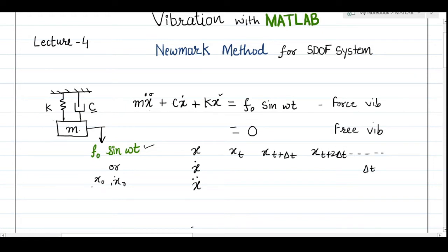What are we doing exactly? If you see the governing equation, it is a second order ordinary differential equation and it is an initial value problem. That means you want to get the response in the time domain, and for that you need to give some initial boundary conditions. Initial boundary conditions means you have to supply initial displacement and initial velocity to your system so that you will get the response for future time steps. So using any numerical method or analytical method, I can get this response.